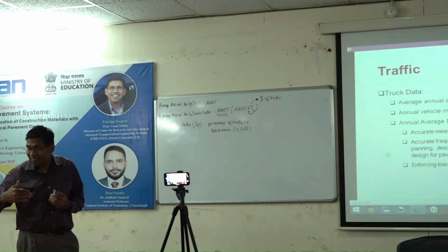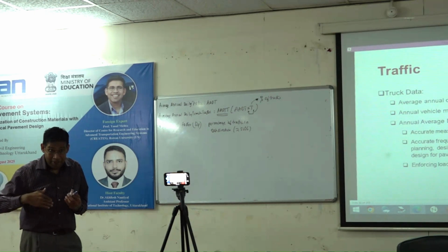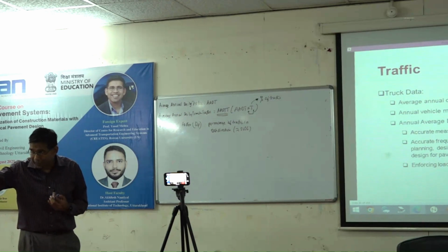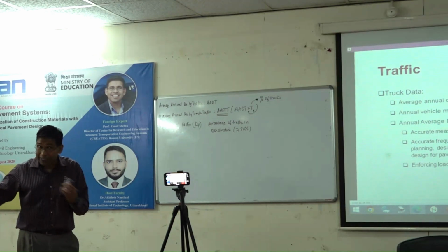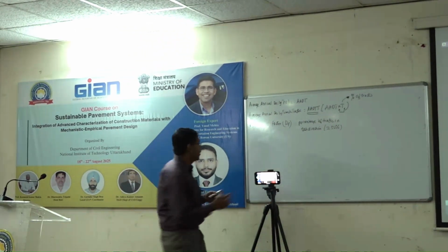Any guesses where? If you are going to a construction plant, trucks coming from the plant carrying concrete or asphalt are always heavier than the trucks going in empty. Does that make sense? That means you may have to design both sides differently if you want to economize. Otherwise, you design the same.